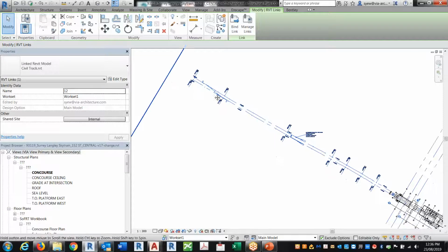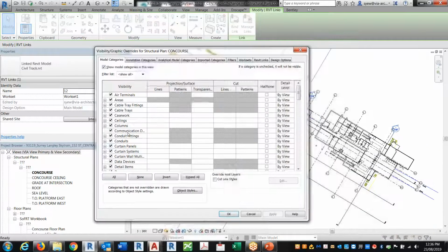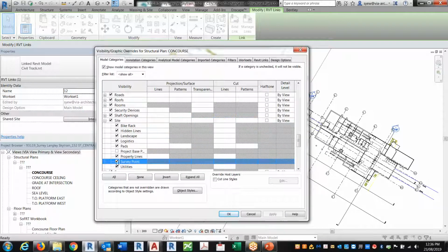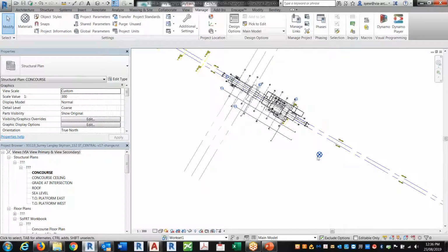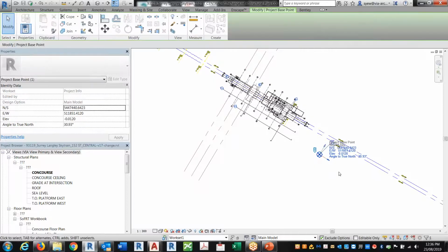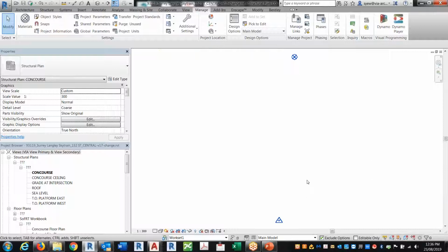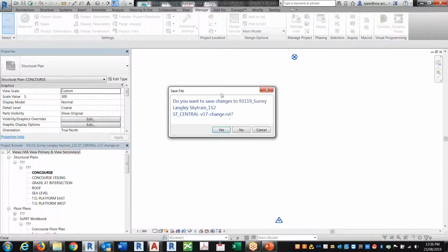I see. But your building point, let's just assume that here I'm just going to go in and turn on the site. Okay? Your survey base point is going to change. Your building project base point, it's right there. It's not going to change. The base building point, it's not going to change. But you notice that here, once I acquire coordinates, it changes the true north, it changes this, it changes everything. Okay? Very, very good that it automatically changed that, so that's a good thing.